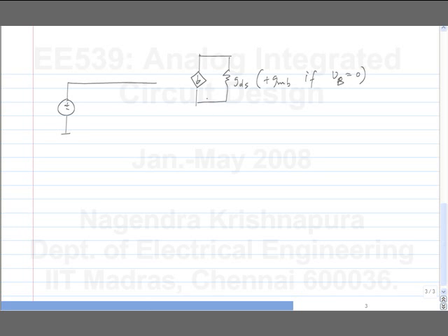So wherever you have GDS, you can substitute GDS plus GMB and you will get the right expressions. Where do we have the parasitic capacitors? Between gate and source and between source and ground. Also between drain and bulk, but that doesn't matter.